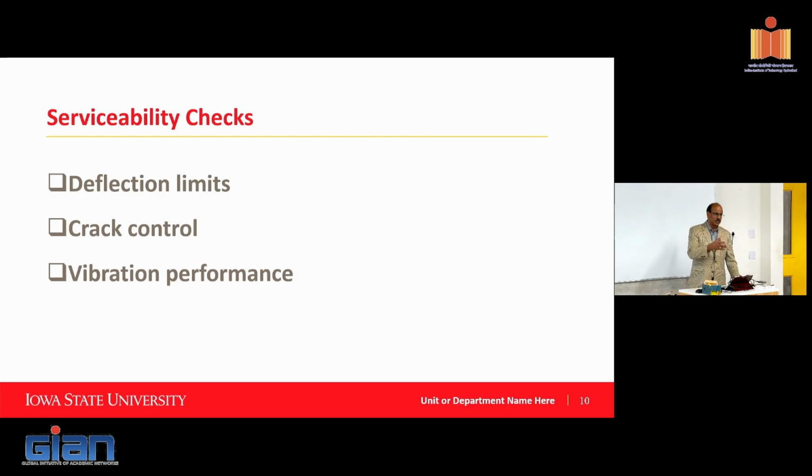And the same applies to UHPC now. They're getting even thinner. In fact, in some cases, people worry about even buckling of UHPC members because they are very thin elements subjected to fairly large compressive forces. So again, it's all specific to those materials. There are things that we should take advantage of, but there are also some challenges that come with that. You have to pay attention to it as well.